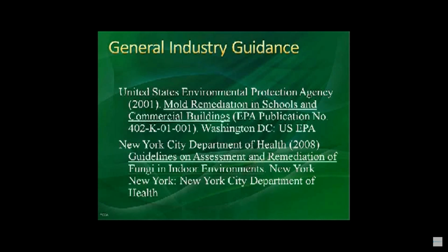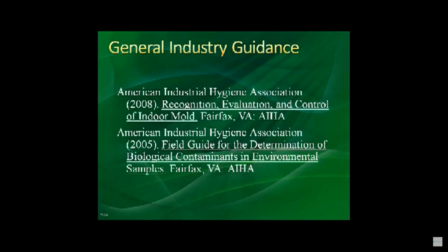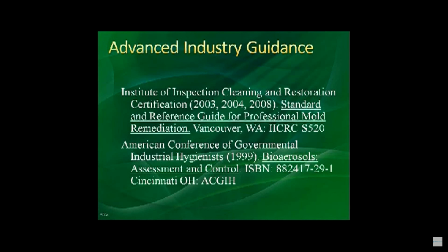Is there rules and laws? Yeah, then there's guidance. We talk about the EPA, New York Department of Health. We call it the mold remediation guidelines, and they're going to be revamped this year as well. American Industrial Hygiene Association, they have a couple different field guides, and all these are able to be gotten. Advanced industry guidance, IICRC S520, ACGIH, bioaerosols. If you're an inspector, these two books you have to have.